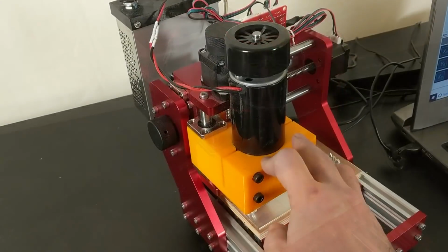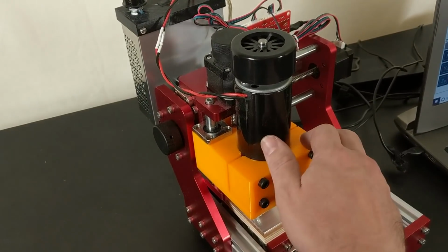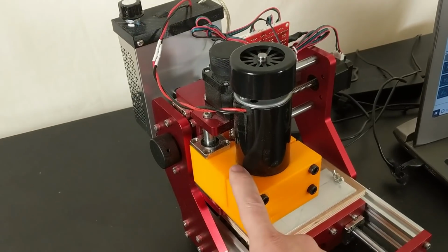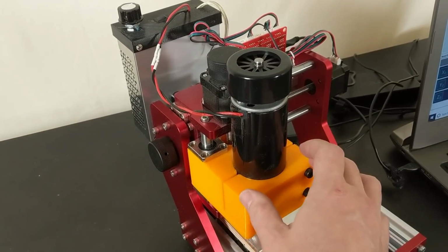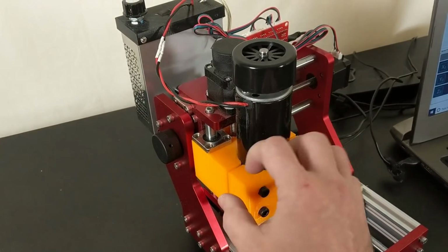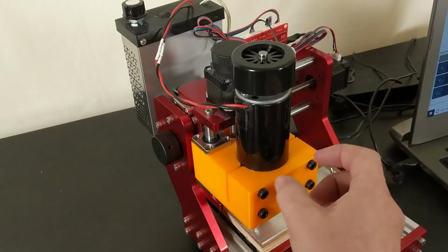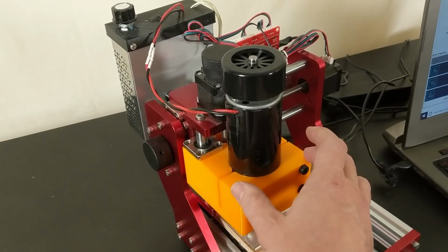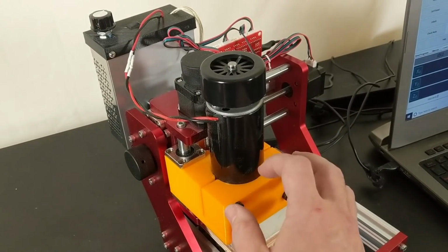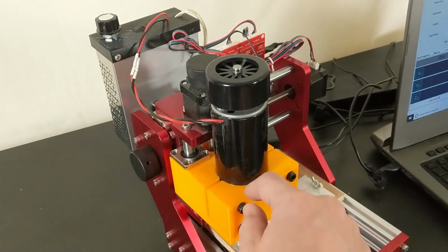If this was going to be my final solution, what I would have done is make it out of probably carbon fiber impregnated PETG, because PETG suffers from the lowest creep, and I think that carbon fiber additives make it suffer from even less creep. So yeah, this could be a final solution. It really is stiff enough, but in my judgment, it's not good enough. I want to make it out of aluminum, so we'll get there.